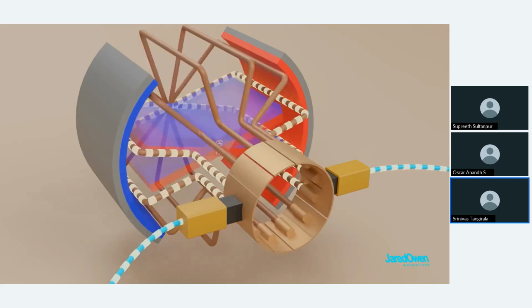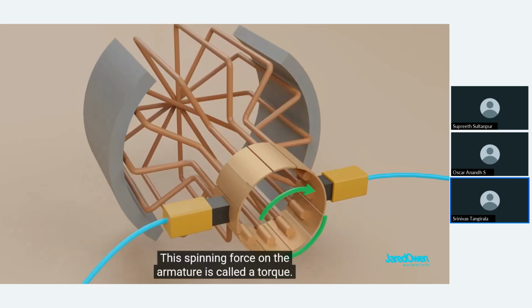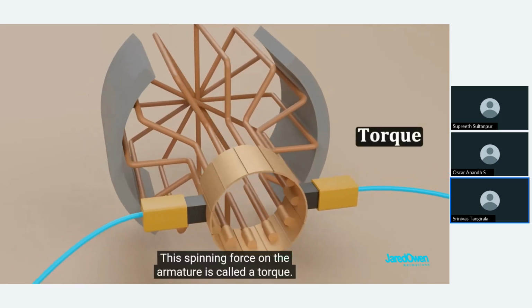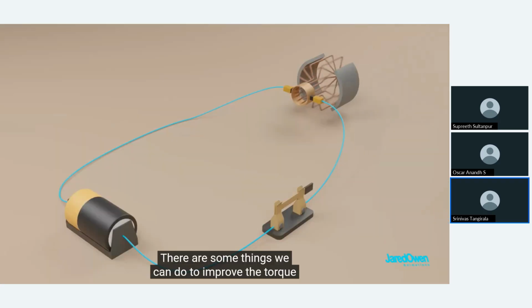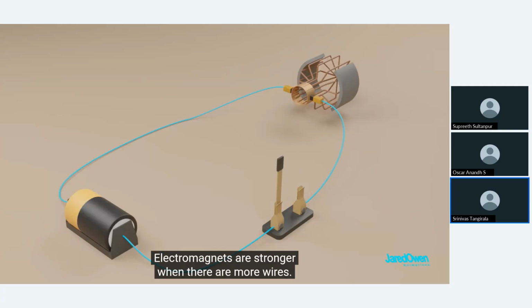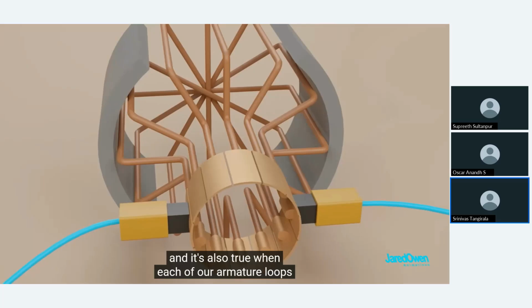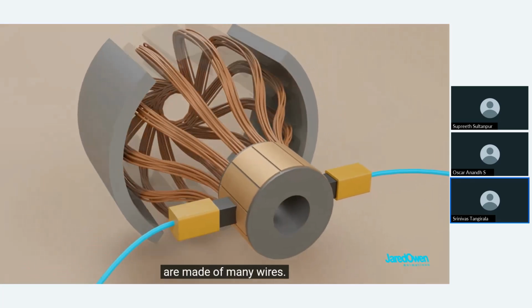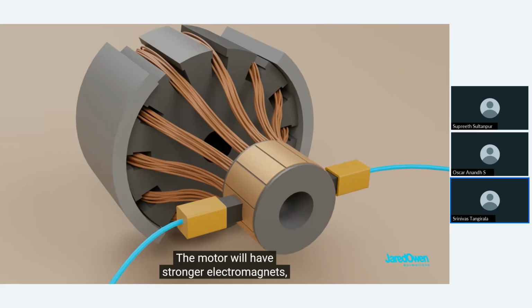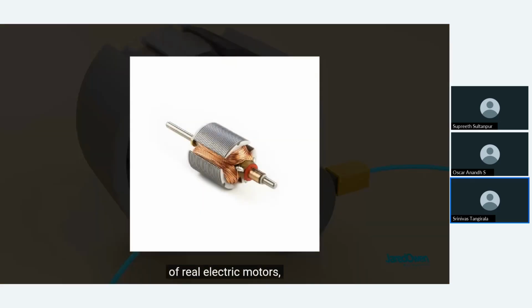So now you can increase further. You can add several armatures, and the direction of the current in each of the armatures keeps changing, and that produces torque. Stronger torque means stronger spin, and that's how the motor works. The more the number of wires or turns, the more the magnetic flux and the greater the torque. So that's how the motor works.